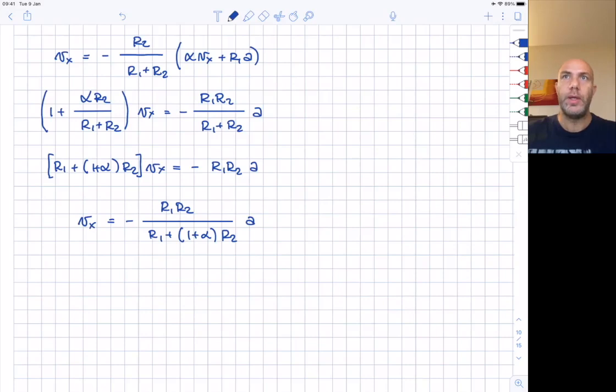generators. The third and last step is the calculation of the real unknown of the problem, because now that we have the controlling variable, also the dependent generator has an expression that is independent of the behavior of the circuit, but depends only on its parameters. So the last step is the calculation of VTH.